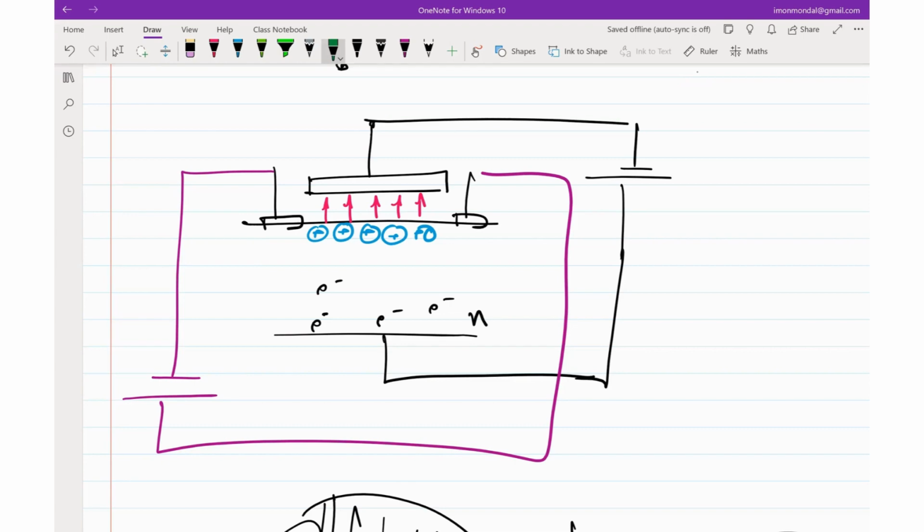An N-type impurity is something which has 5 electrons in its outer shell, and a P-type impurity has 3 electrons in its outer shell, which essentially means that you get a hole out of it. I assume you know this. For example, boron is a P-type impurity. If you dope a piece of silicon with boron, you are going to get an overwhelming majority of holes. And if you dope it with arsenic, like the example that I took, you are going to get an overwhelming majority of electrons.